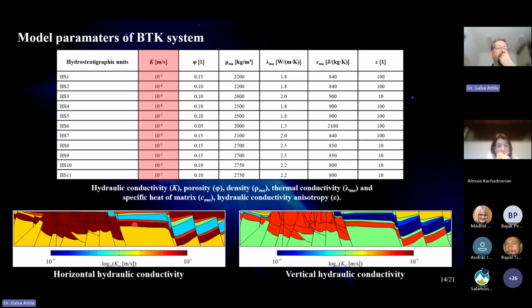So for the sake of simplicity, the main aquifer of the karst system is the Triassic karstic carbonate, which is in unconfined form in the western part of the system, but it is confined by the Oligocene clayey aquitard in the eastern part of the karst system. So I think this is the main difference between the 2 parts of the karst system. The western part is unconfined, the eastern is confined.